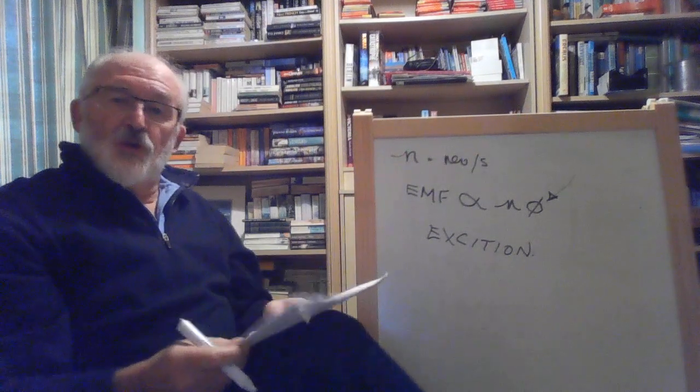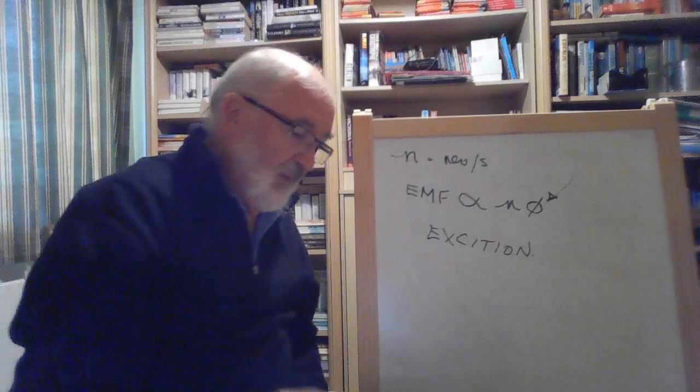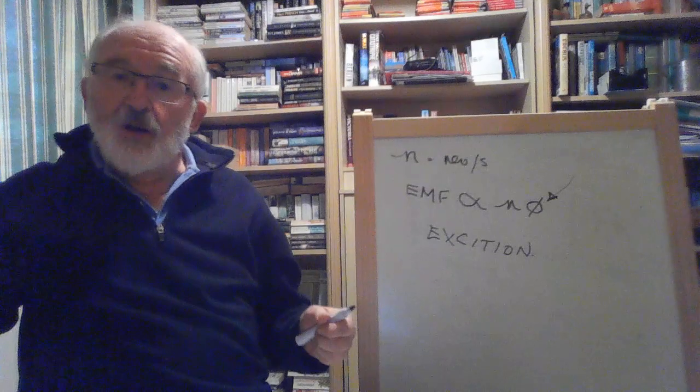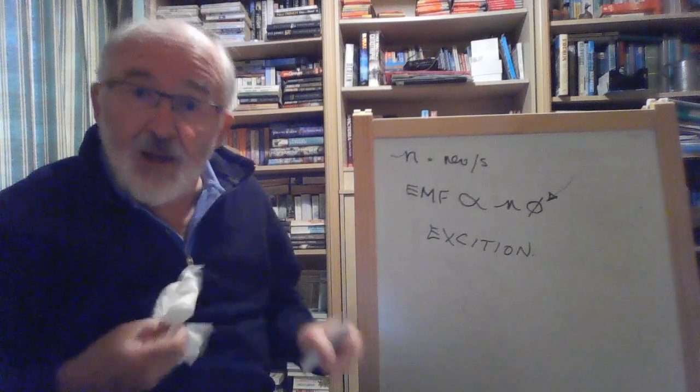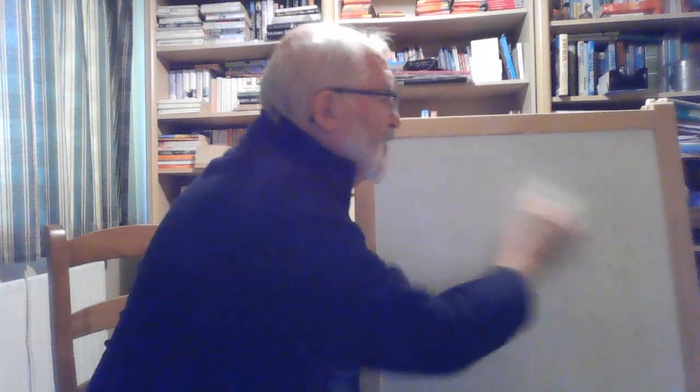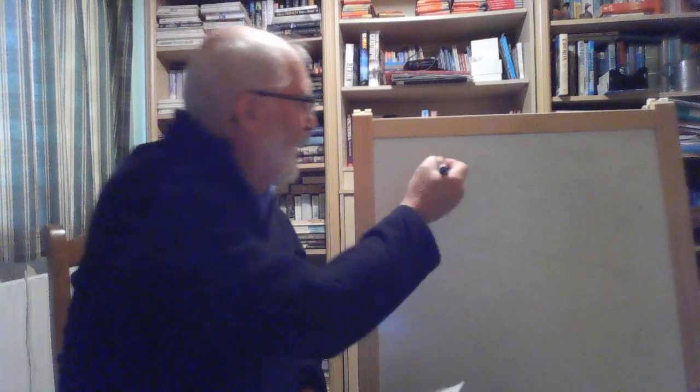So as well as controlling the line voltage, we also need to control the other variable that we've already mentioned to the surveyor, and that is the frequency of the system. European frequencies tend to be 50, American tends to be 60. Possibly 60 is probably a little bit more efficient, but that's by the by. So we need to control the frequency at which our generator works.